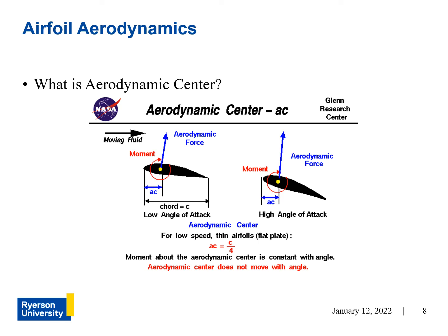Okay, so what is aerodynamic center? Aerodynamic interactions between the flow of air and the airfoil result in the generation of lift and drag by the airfoil. These same aerodynamic interactions also create a pitching moment on the airfoil, and for airfoils with positive camber, the pitching moment is negative, meaning the airfoil tends to pitch down. And that's why it's important to have a tail to counter that moment.